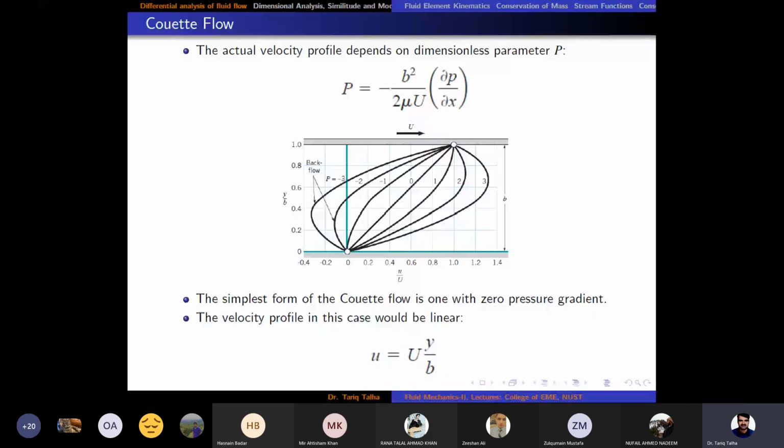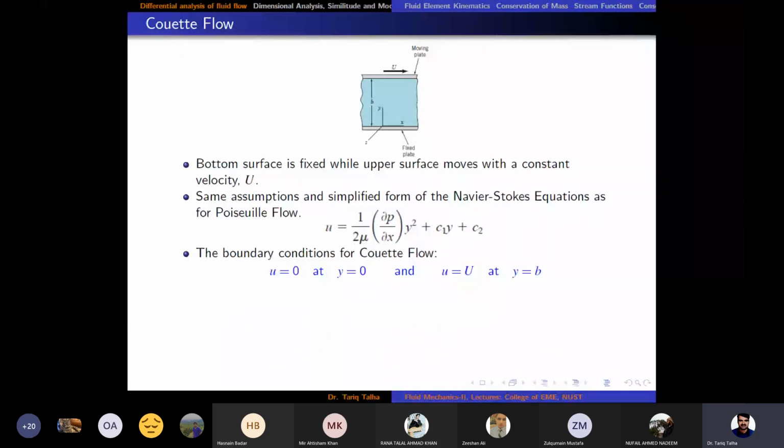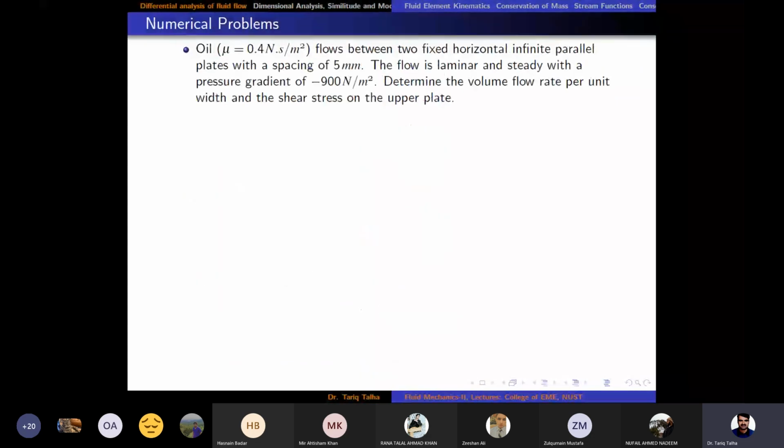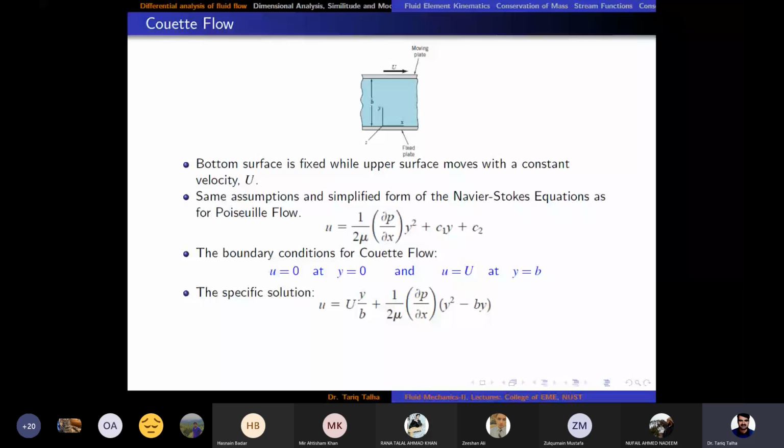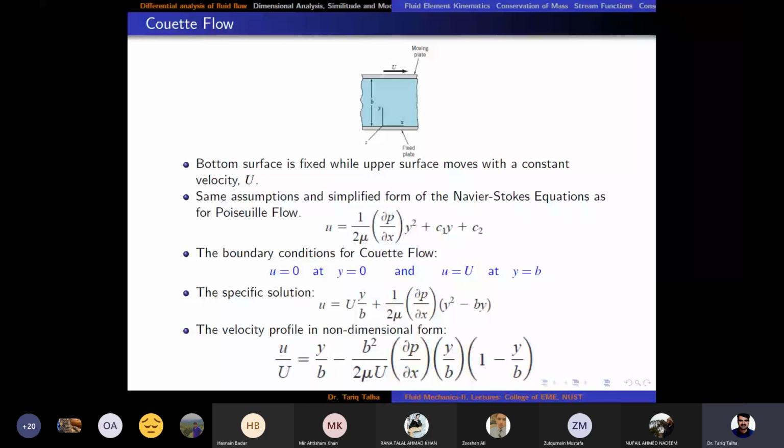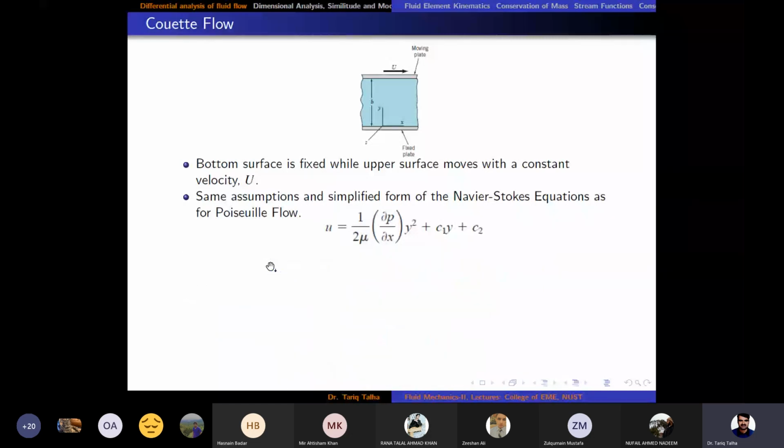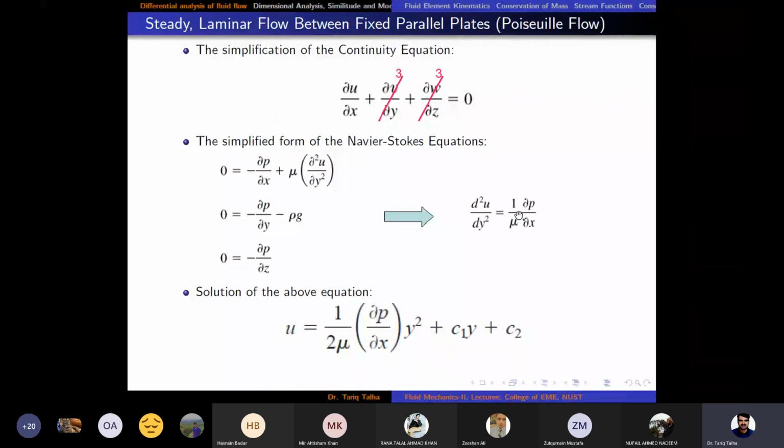Now this was just about the derivation of the Navier-Stokes equation for the incompressible viscous flow, right? As you can see, we can only get the exact solution for very simplified cases. We cannot get the solution when we have unsteady flow, or multi-dimensional flow where u is also a function of x, y and z, which is the case when the flow goes through certain turbomachinery applications, or flow over an aeroplane or a vehicle. In those cases, we cannot get these velocity profiles, which are obtained by converting the governing equation into an ordinary differential equation. Where the mouse cursor is, you can easily see that this is an ordinary differential equation, and we can get the exact solution by integration.